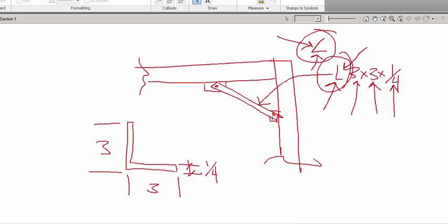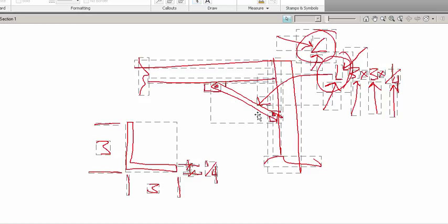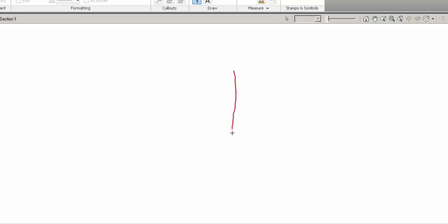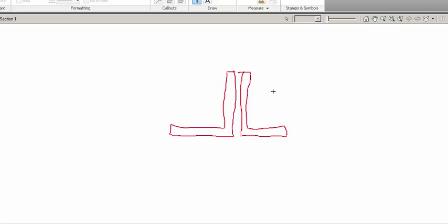However, what is also cool about angles is sometimes they can be used in tandem. So instead of just having one structural member, they can take angles and butt them up with each other, which by the way also forms a T, so a T can replace this, but we can use angles to reinforce or have double strength. So let's say there's a steel plate and we have an angle on each side for one of those kickers or struts that I showed, and we run a bolt between the two.